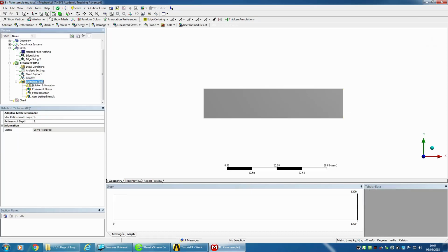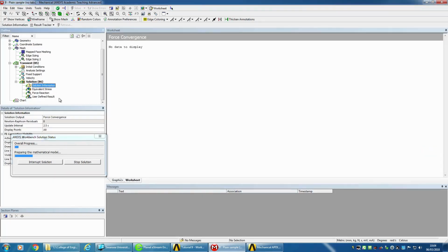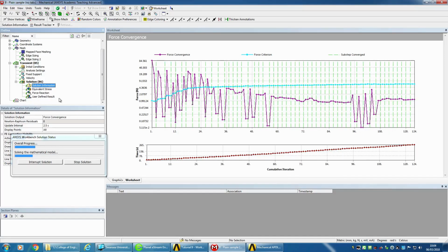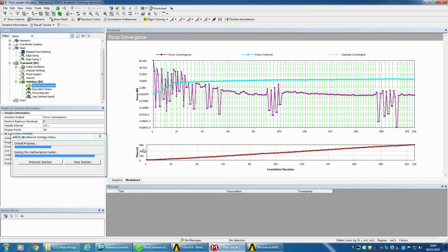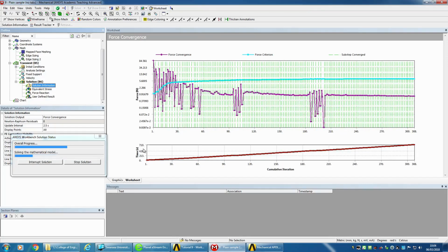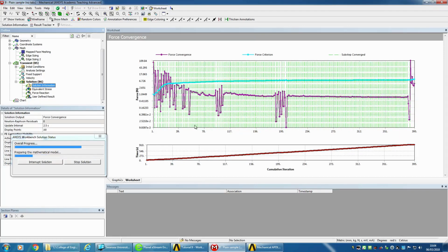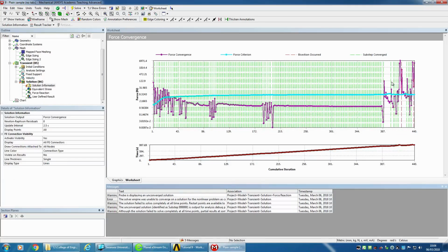So you can solve that immediately on that very coarse mesh, and I'm hoping that we should see under solution information that we are running very quickly. So the simulation time there, you can see again goes to 380, much larger. They are larger time steps, but the mesh is much coarser, so the whole thing is running a lot quicker. Lots of green on our graph, except at these last steps. So you might get that in your simulation from now onwards.